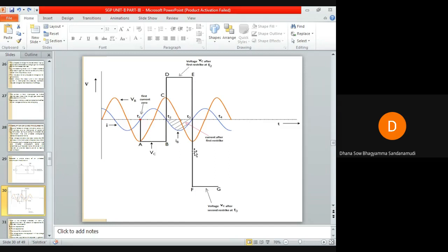If the breaker restrikes again at this point, the events of B will repeat on an even more formidable scale, as the voltage swing will now be 8 times the maximum VB, and the line may then be left isolated at a potential of 5 times maximum VB to earth.